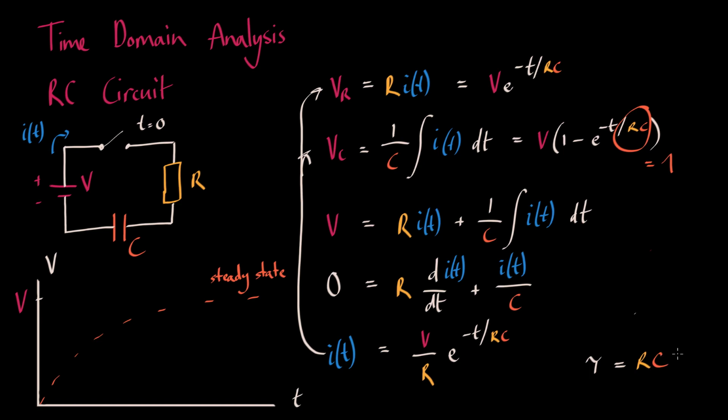The important takeaway from this is that for capacitors, there cannot be an instantaneous change in voltage. It simply cannot occur. The capacitor gradually gains and loses voltage to a point of equilibrium, in line with this curve and the corresponding time constant demonstrated.